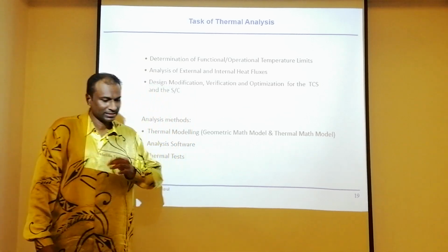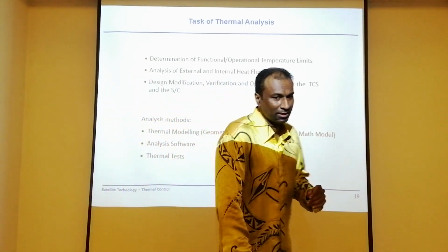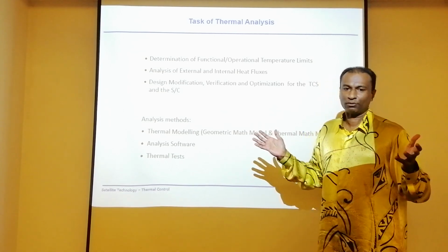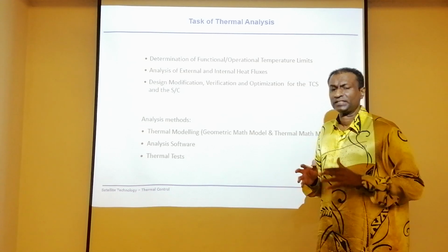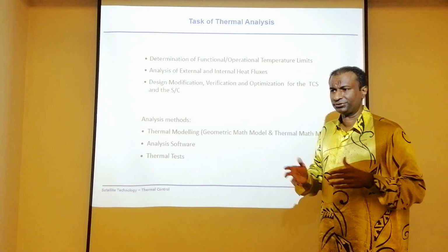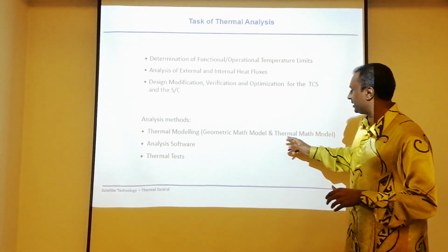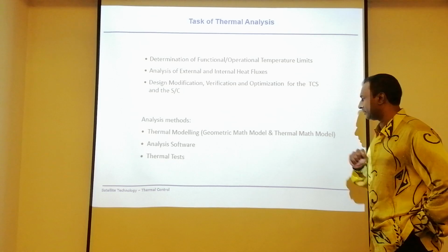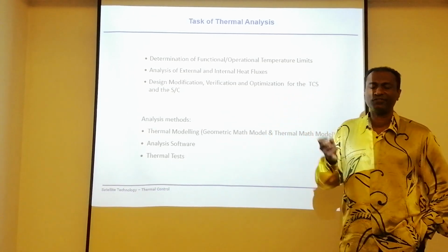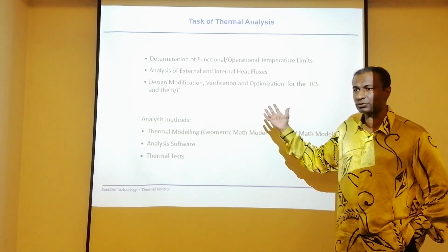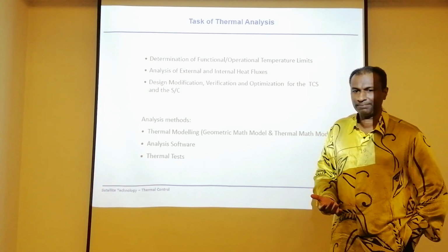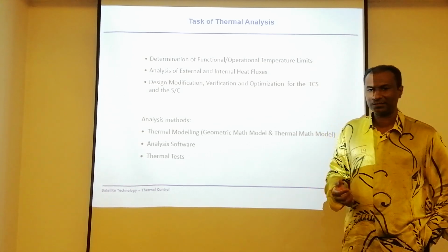The thermal math model is slightly simplified; we can use the spring method basically. We can use spring laws, parallel and series, just like you have done in your electrical courses. For analytical solutions, this thermal math model can be applied. Then you have analysis software where you can use finite element to do this approximation. It's quite common. Thermal test, as I said, if you have the devices already designed, then we can look into the thermal test that you want.